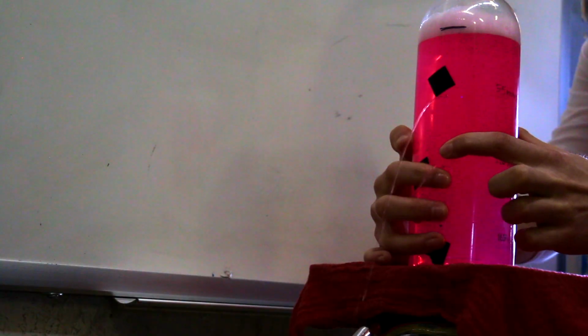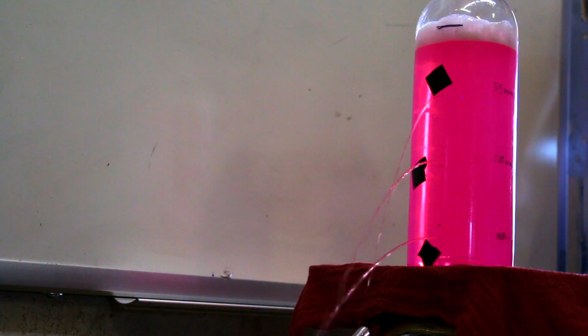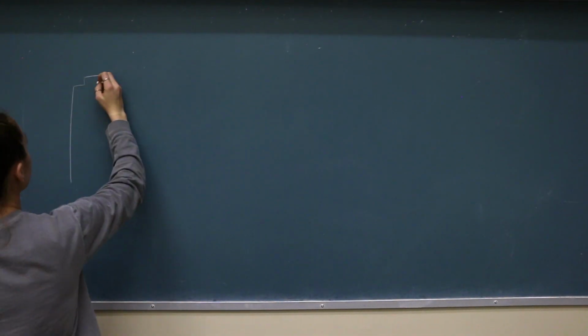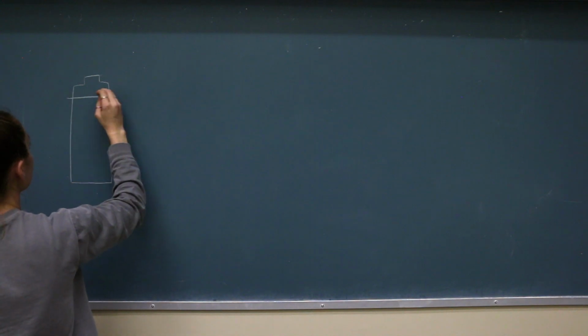This is due to the increase in pressure as the height of the fluid above the hole is increased. The previous derivations prove this idea since it demonstrates how the pressure at a certain point inside of the liquid is related to the height difference between the chosen point and the water line. Building on top of that is the relation between force and pressure. Since force and pressure are directly related, and in our demonstration the area stays constant, the force at the bottom is greatest for the stream of water coming out of the bottle.